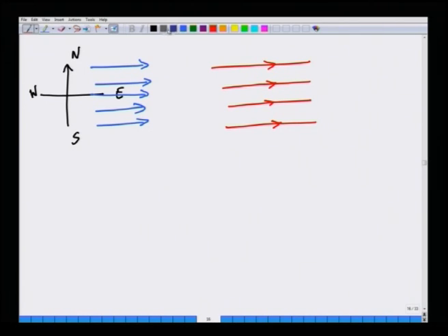Let us look at path lines. Path lines are, you take any point and you inject dye at that point at time t equal to 0 and watch its motion at a later time. So, this point would have moved elsewhere at a later time, but it will also be a line that is parallel to the streamline. So, it will be identical to the streamline, because you can inject a particle here, it will move exactly parallel on that streamline itself. So, in a steady flow, in the Eulerian sense, the path line and streamlines are the same, and a streak line will also be the same,